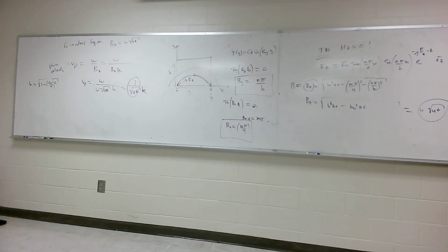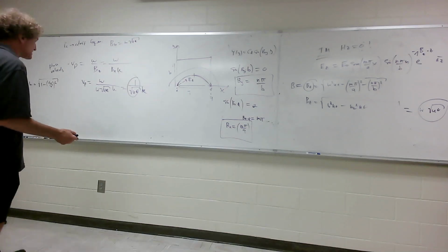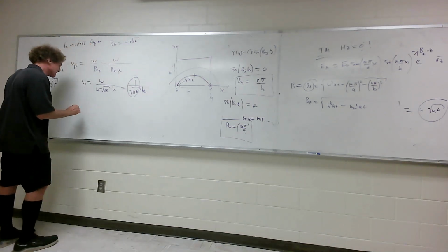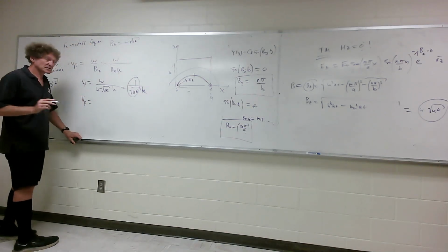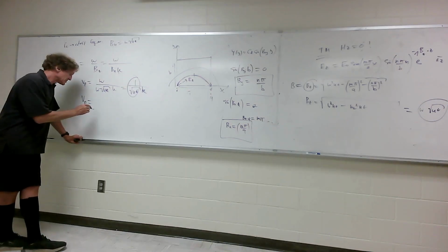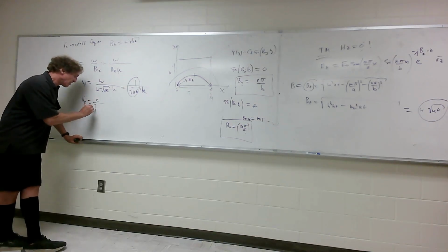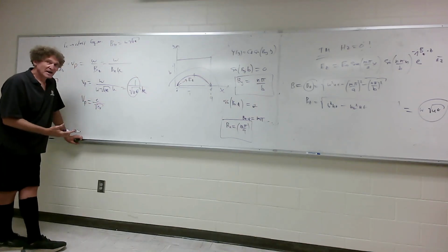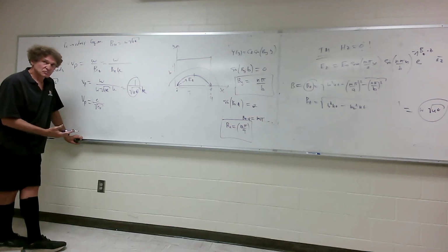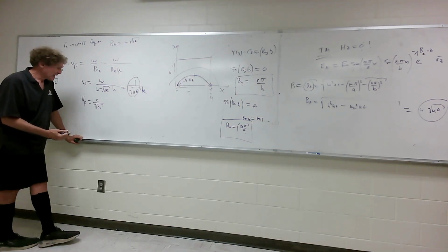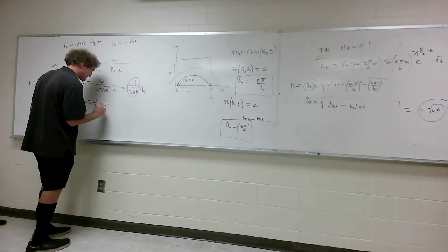It is the velocity that the wave is propagating with in free space, if there was nothing confining it. A lot of times they write it like this: the phase velocity, which is not the velocity of energy, is equal to c over the square root of epsilon relative, divided by k. The reason they do that is you almost never have magnetic materials in waveguides, so they assume mu relative is 1.